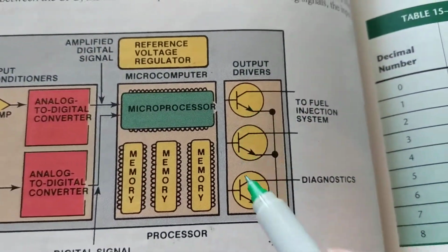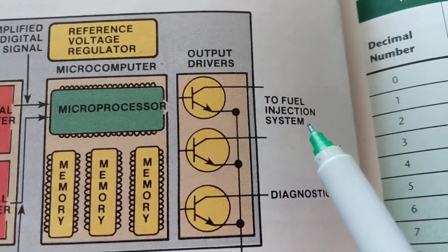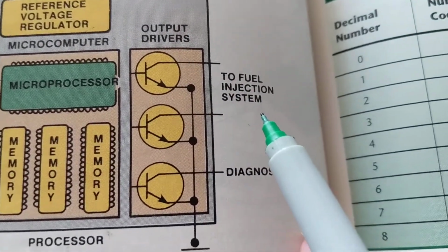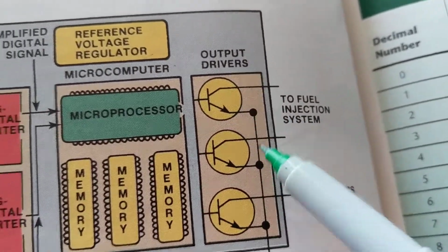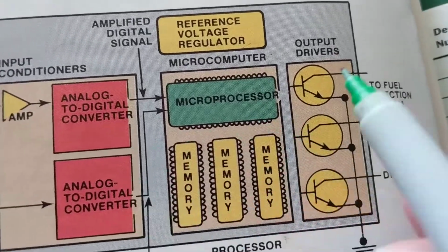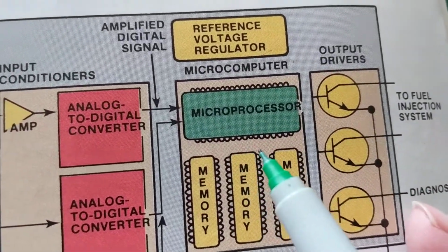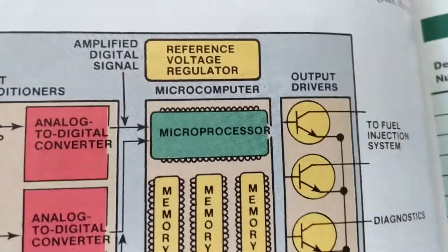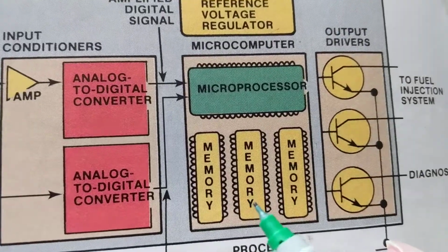And then finally you have all these drivers. If you were wondering what drives the fuel injectors, this is what drives them. It gives it a ground. The transistors going on and off. This is what's inside the computer. And this is what I used to spend time on, fixing these things, until the customer said no, it's too time consuming and not cost effective.